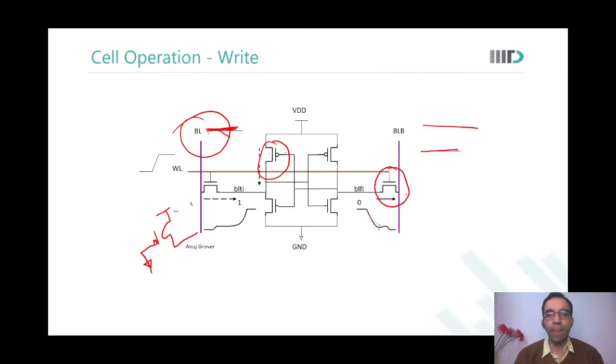Ranjit? Sir, I too had the same doubt as what Raghav said. So we start the write cycle from the discharging node, and once this node discharges, it drives the other inverter, which charges the other node. Yes. Okay. Yeah, understood, sir.